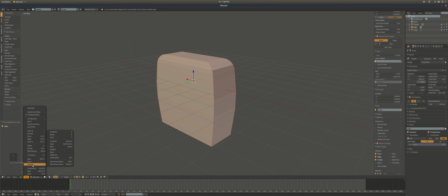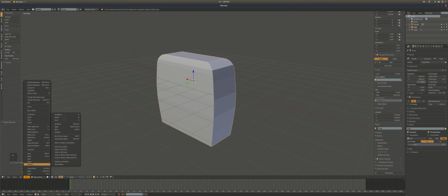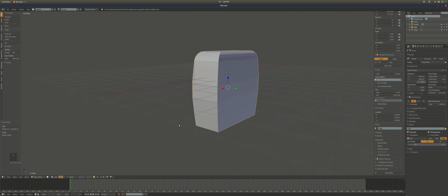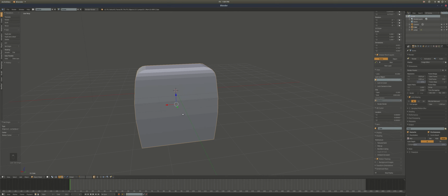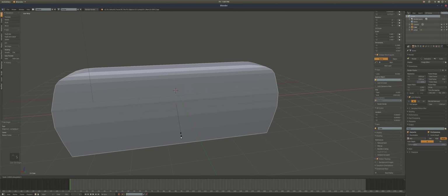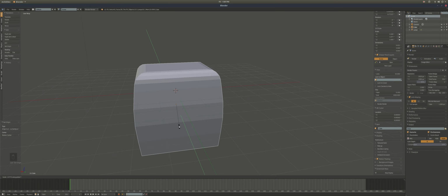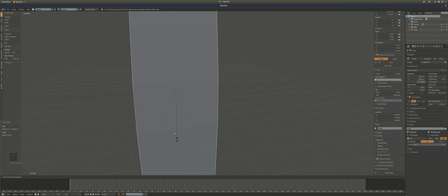It's under Mesh Transform. When you're in object mode, Mesh Transform, and you can say where the origin is. So this widget, where that's going to be on your object. So you say, let's see, transform. If you said origin to center of mass, it's going to drop that back to the center of mass of the newly modified object. So if I said scale X or Y, nope, Z, sorry.